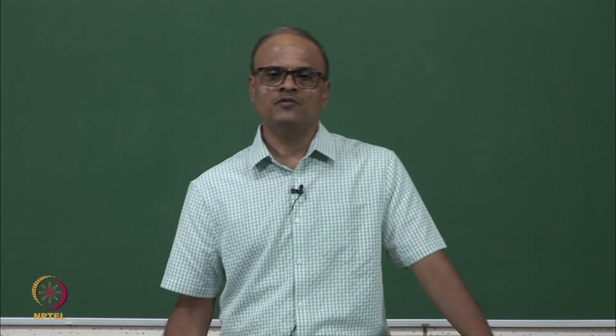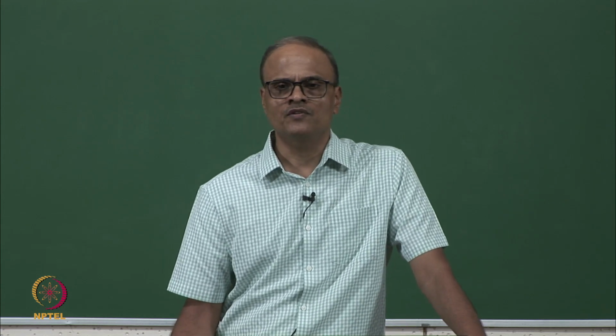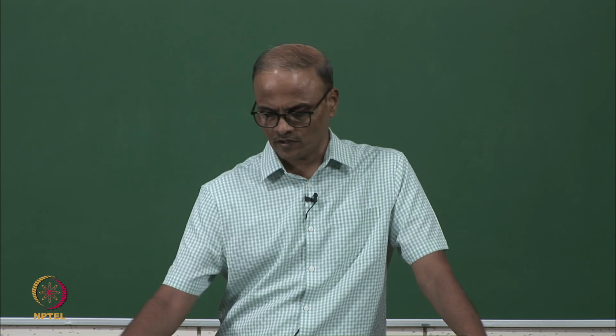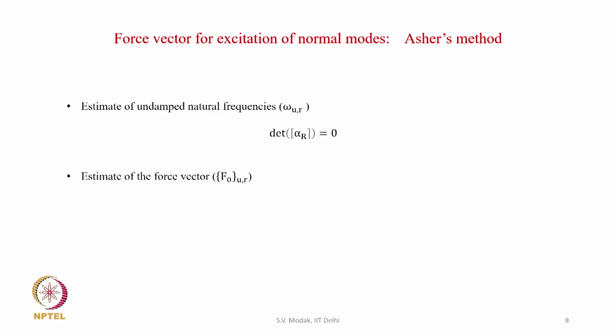So once undamped natural frequencies have been found, what can we do? Now we can substitute the undamped natural frequency in the fundamental relation to obtain the force vector. Let us say that the undamped natural frequency is represented by omega ur. The subscript u is used to represent the association with the undamped mode.